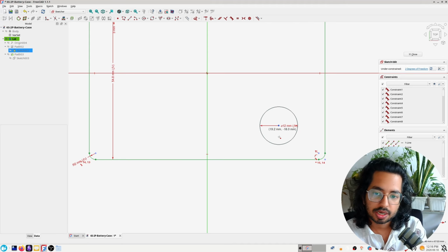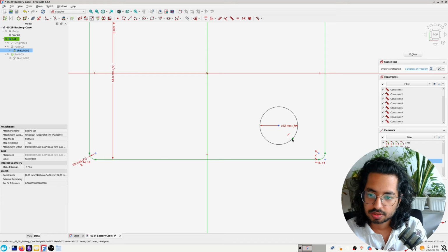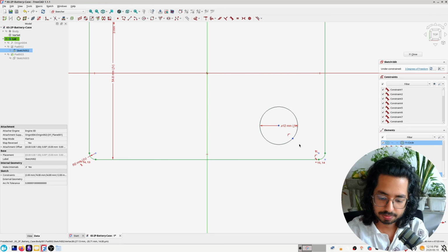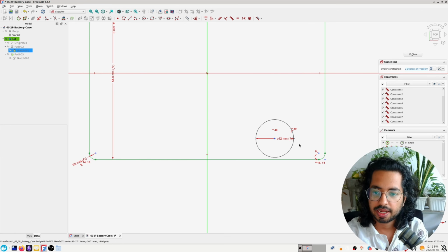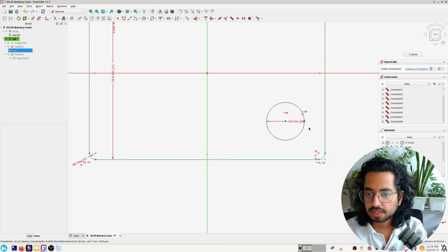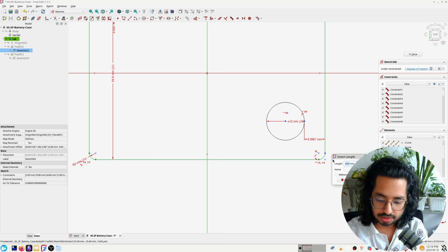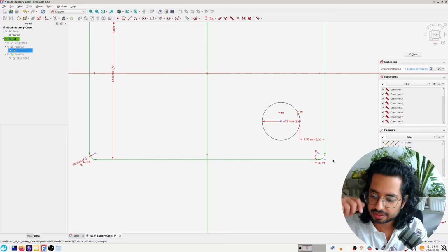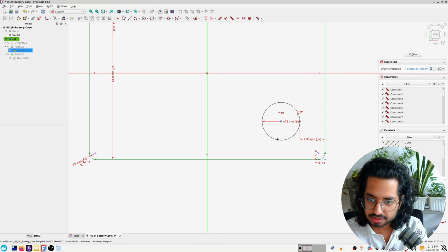You again get a dot, add this dot here, and this dot will be moving, so I can press H to get it horizontally here, and now we can put the distance from the edge. I'll press L equals to, and constraints. I'll just use the same edge distance because I have enough clearance to rotate, or let's add a bit more, or we'll see about that.